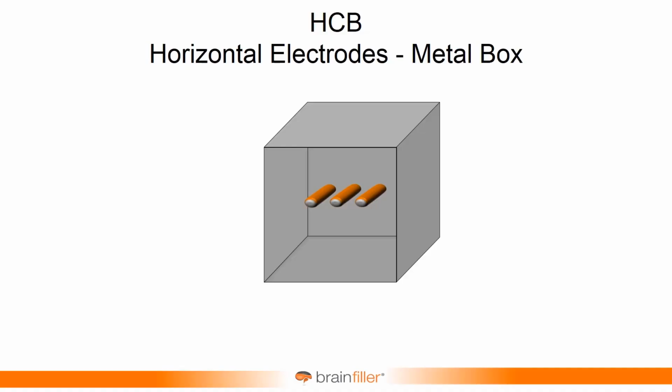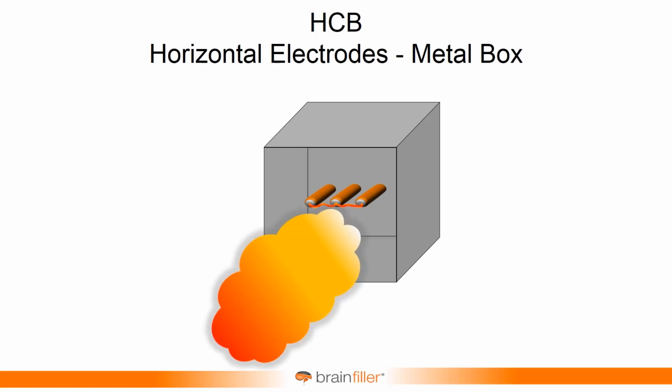And then we have the horizontal electrodes. And these are the electrodes pointed at you. And this is the most aggressive of the tests, because what's going to happen when you have horizontal electrodes, and this might be like bus stabs or something like that, and I have a few pictures I'll show you, is that the energy is going to run along the horizontal bus, and it's going to come off the end, basically being directed at the person that may be in front of it. Hopefully there won't be anybody in front of it. You should be standing off to the side, but it's coming out more aggressively. And so you have the arc, and then you have the energy being directly ejected straight out of the enclosure. And as I said, this is a lot more aggressive arc flash setup.